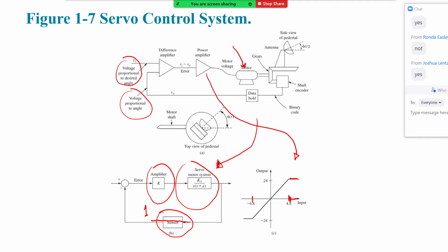I might look at this and say, oh, because the amplifier is saturating, it's causing a behavior that is not acceptable. Or it might be that because it's saturating, it's making the response faster, and I'm seeing a little bit of oscillation, but this is acceptable considering it does not last a long time, for instance.